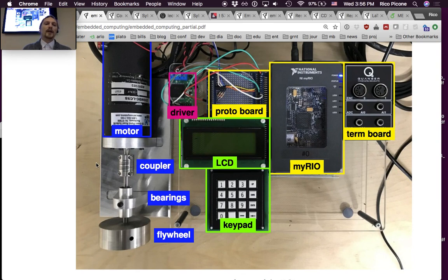We have a flexible coupler, which we'll talk more about why we need, but essentially you're always going to find, when you have real systems and manufactured systems, the alignment's not going to be perfect. There's going to be misalignment this way, and then there's going to be misalignment angular-wise. So this flexible coupler allows you to couple those shafts with some play. They don't have to be perfectly aligned.